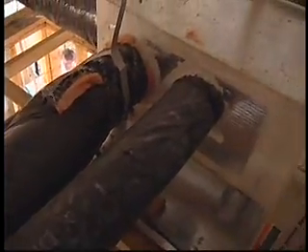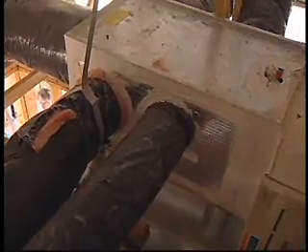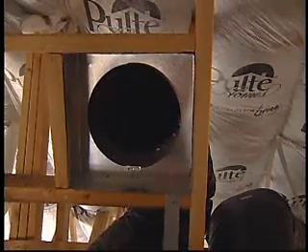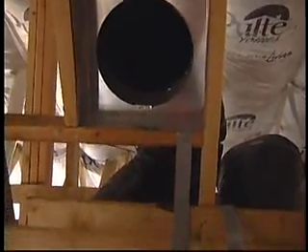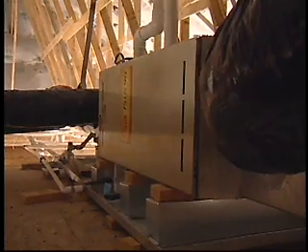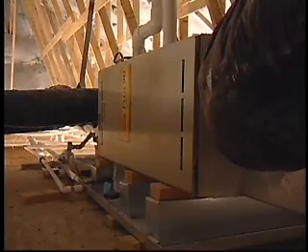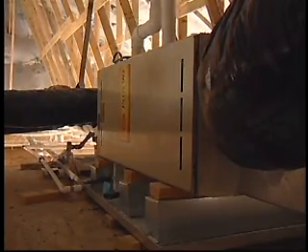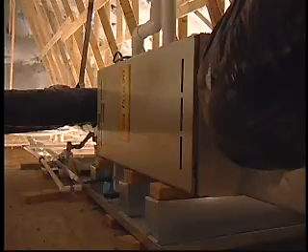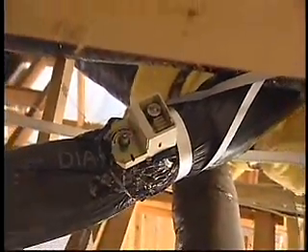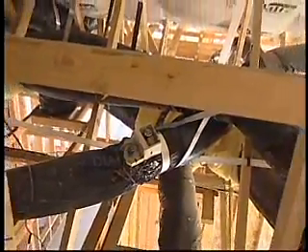When you come to a place where you need a sharp turn, use a metal elbow there instead of just trying to kink the flex duct over. Make sure it's sealed well. Of course, in this whole thing, we're getting the right size air conditioner in. We're going to have ducts that don't leak. And at the same time, we're going to have to make sure that we have the right amount of airflow across the coil. We're going to have to make sure we have the right amount of refrigerant charge. One of the ways to make sure you've got proper airflow across the coil is that there are no kinks, crushed areas, and misinstallations that cause that reduction in airflow.